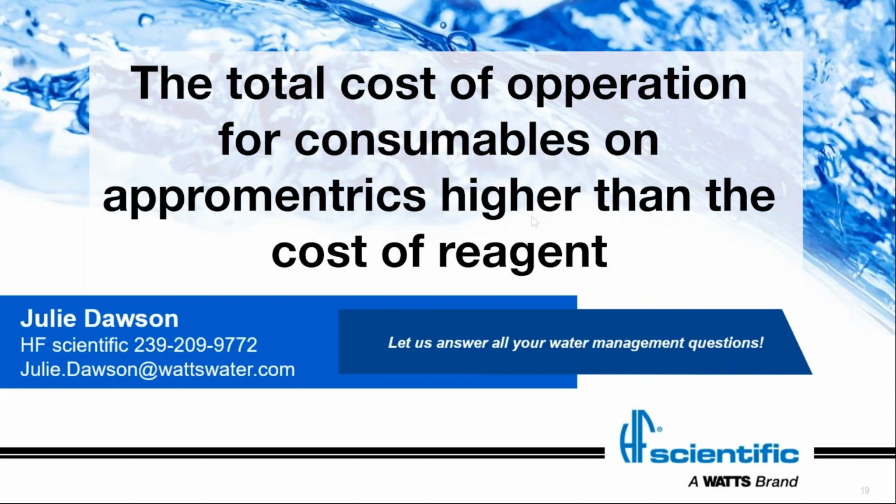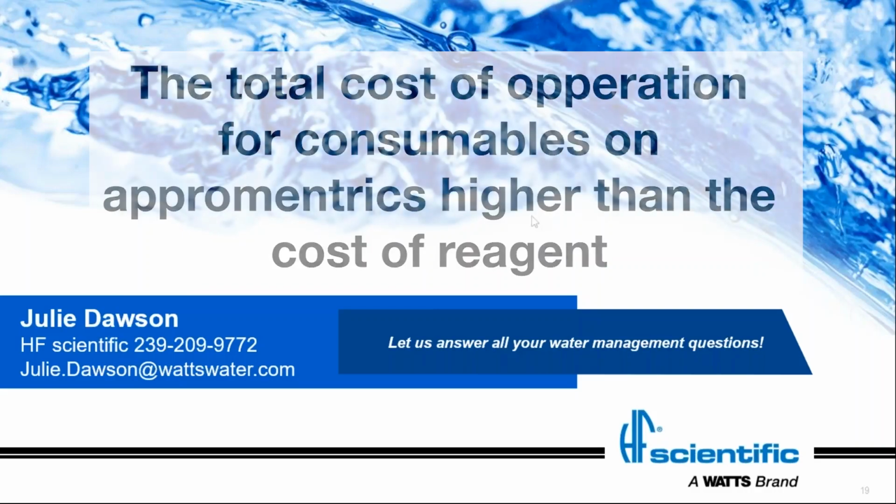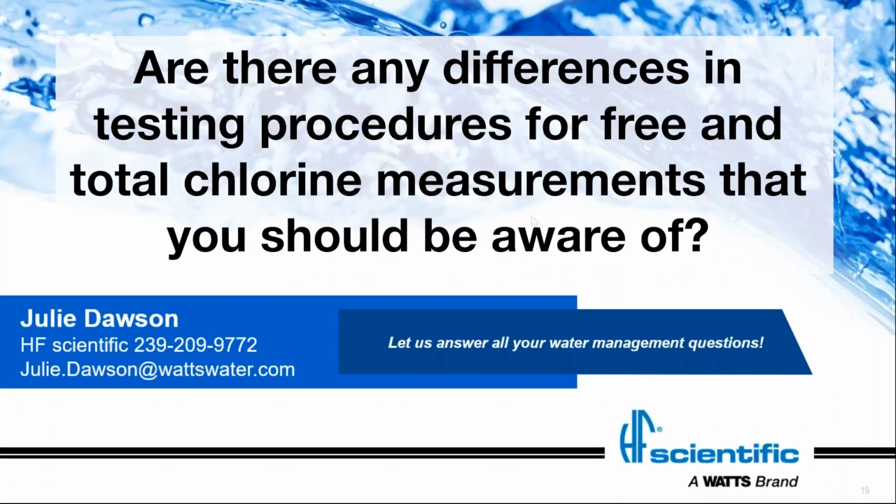But understanding how long your probes in Amperometric last in your application, or looking at the manufacturer's recommendation on when to replace those probes, is key to understanding what those consumable costs look like. In most applications, I find DPD to be less expensive overall, and you can budget for your costs because you know exactly what they are going to be, but there may be some manufacturers where it is less expensive. This is going to be specific for each one.